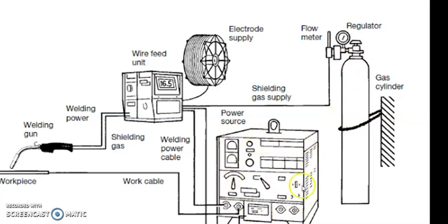We are already using a welding transformer, and this transformer is also a step down transformer, just like in arc welding. From this, again just like arc welding, the negative cable is directly connected to the workpiece, that is, the cathode, and the positive terminal is connected through this wire unit to the welding gun. So it is the same as arc welding, but here is the difference: